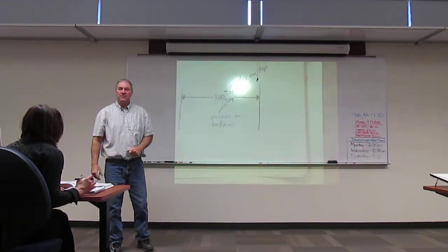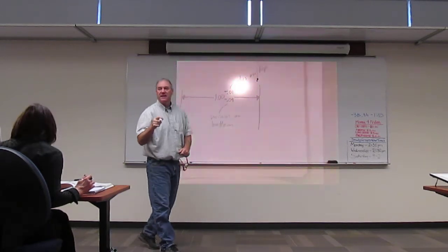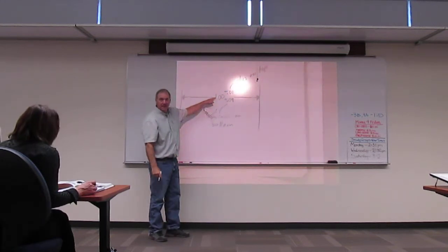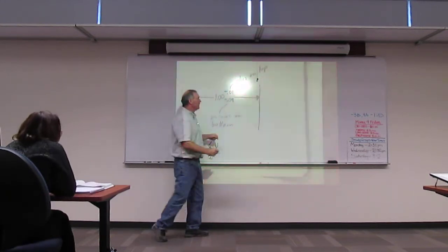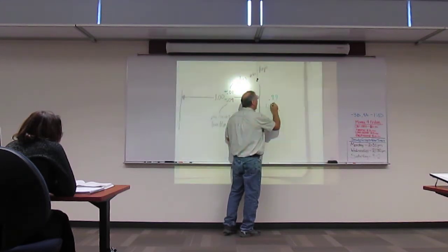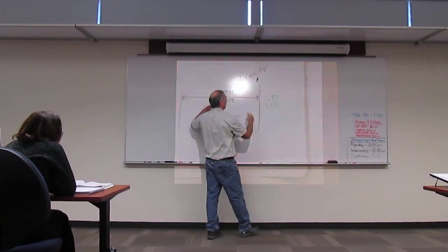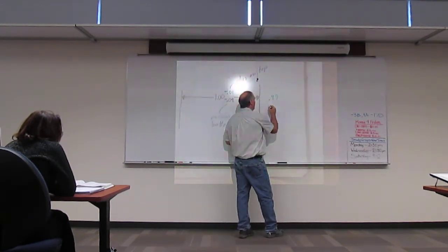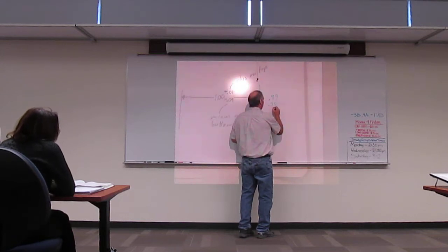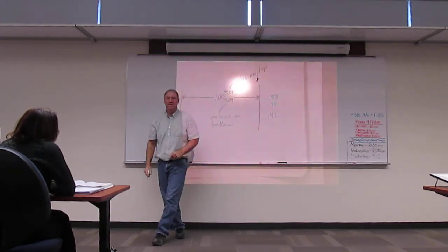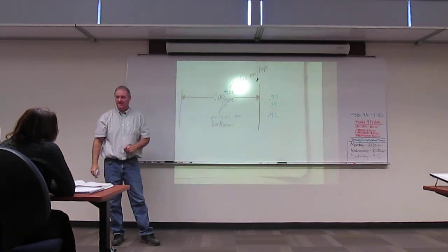Okay. So what you would then do is hand calculate your limits. So if I had a minus minus here, the craftsman is then going to build this at 0.99, 0.98, 0.97, 0.96. Those are the acceptable sizes. Do you see where I get those numbers?